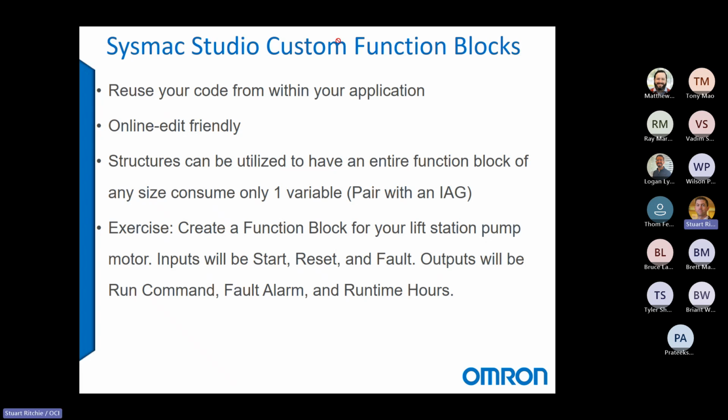So we can make custom functions or custom function blocks. Really, the only difference between them is you use a function block when you need to retain something for the next scan cycle. So it will allocate memory that it keeps for that function block. Functions, on the other hand, don't need to retain anything for sequential scans. So if you were doing a simple math operation, spitting out the result, that could be a function. If there were timers and counters involved, you would want that to be a function block so that we could keep those values in memory.